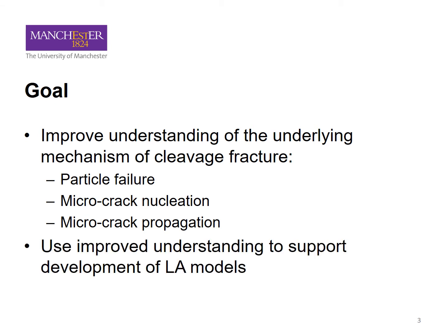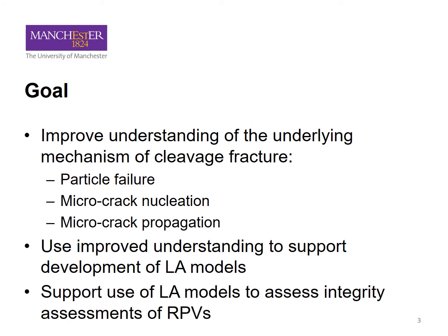And then use this improved understanding of the above to support the development of local approach models, where local approach to cleavage models try to predict the probability of cleavage based upon the stress and strain fields at a given point in a material. And improving the models would support their use to assess structural integrity of RPVs.